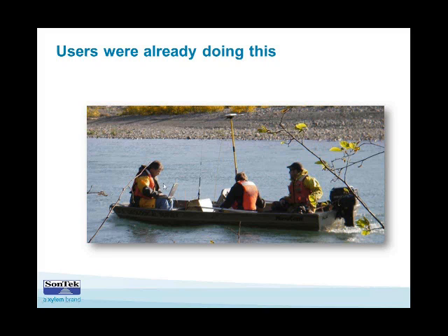And with those two tools available to users, they were already doing hydrographic surveys on their own with River Surveyor Live and some with the CastAway CTD also. River Surveyor Live maps velocity profile and depth with latitude and longitude, and these can be exported out of River Surveyor Live and used to make bathymetric maps or hydrographic maps.